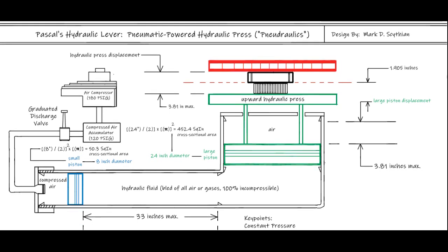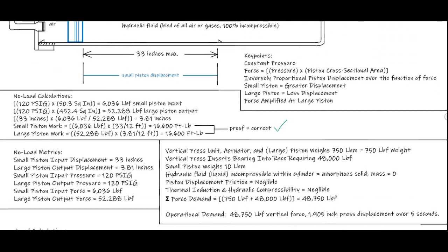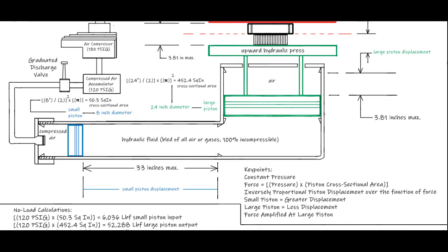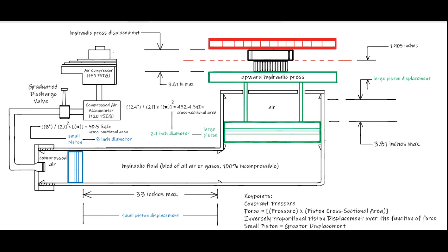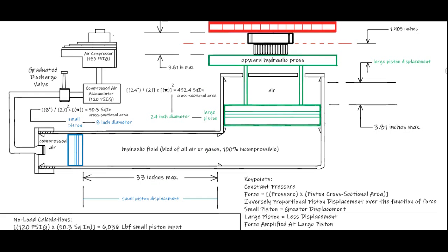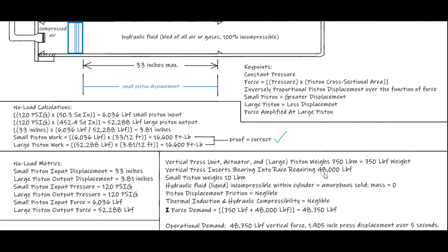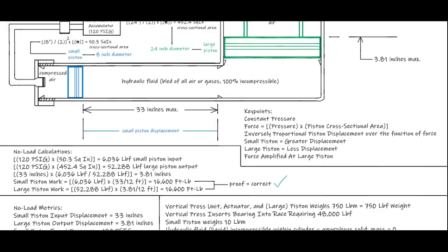So moving on here, we will use a specifications to put this device into good use. For example, in this application, we will be pressing a bearing into a bearing race as part of automation assembly processes. So the specifications as calculated in the assembly design require 48,000 pounds of force to press the bearing into the bearing race.